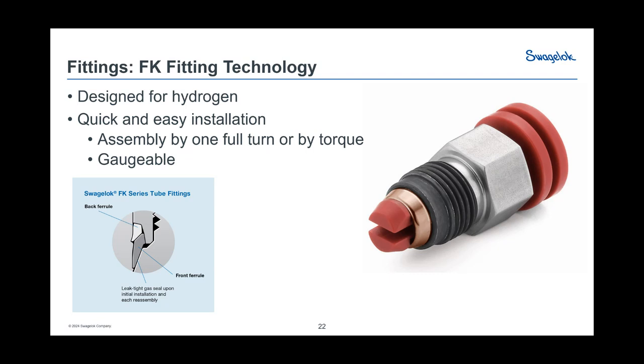We did that because we knew that if we were going to be dealing with vehicles, there were going to be components that Swagelok wasn't going to make. We weren't going to make tank valves, and we weren't going to make a variety of other types of components that went onto vehicles. So we made this so we have the ability to license it out to others, to be able to put our port end inside of their components and reduce the number of connections inside the systems. So that's what the male end is all about.